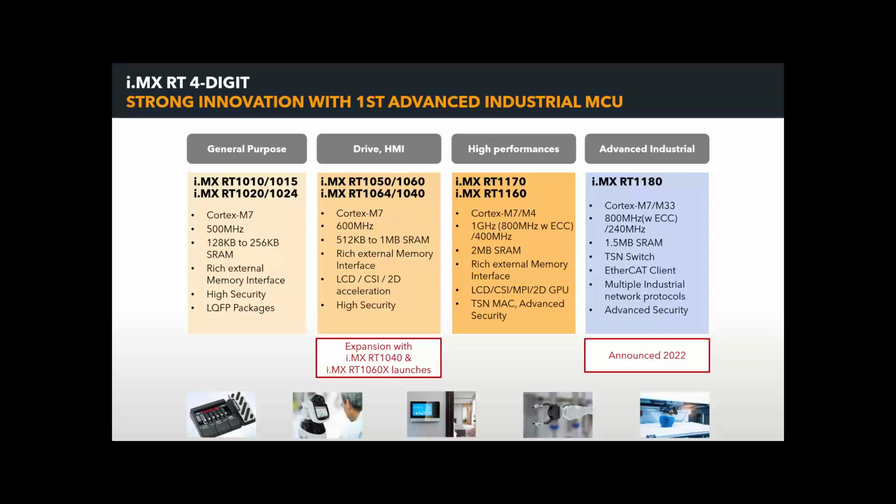And then moving on to the right, that will be the RT1050, 1060. So those ones, we managed to add more driving and HMI capability onto it. And by saying that, I mean we have more waveform output capabilities with those devices, like the motor control PWMs. We also have 2D accelerations for either camera interface with CSI or the LCD display.